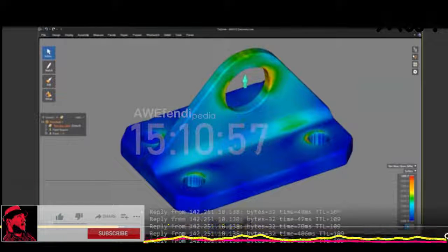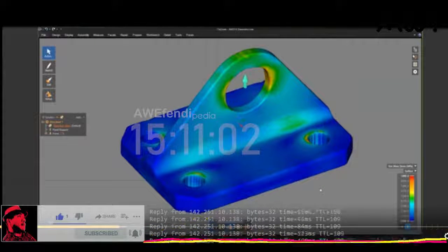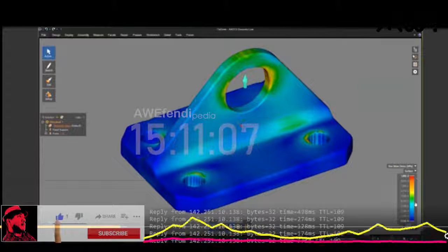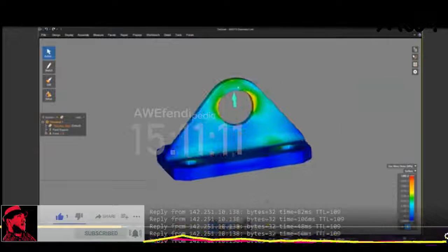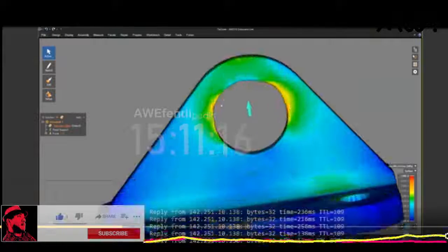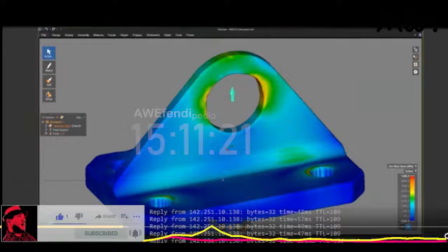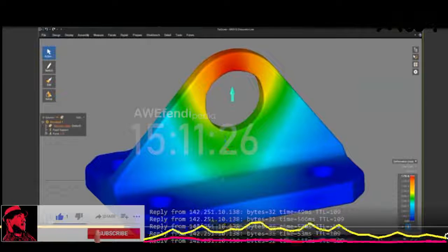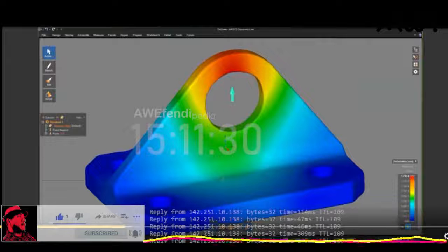So what I'm looking at right now, take a look at this. I'm looking at the stresses already on this scan model. This is a scan that I scanned in. I quickly healed it, bored out some holes, applied some boundary conditions, and I can already tell where I'm getting a lot of that stress. You can see that if there's a tie down here pulling on it, I'm going to get the stress from the sides. That's how you see this circle become this weird oblong shape. I can quickly take a look at the deformation as well to understand, okay, when it's pulling on it, this is the type of behavior I'm going to see and expect for this particular part.